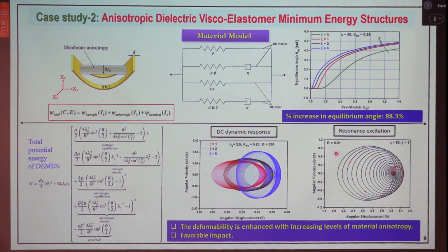Very simple use is that I will tell you, this Poincare map is used to characterize the stability of the system. If you are considering a non-linear dynamic system, if they form a closed loop, it represents that the system is quasi-periodic in nature. Stable quasi-periodic, you can say. If this Poincare map forms a large number of distorted points here and there, it means that the system is aperiodic in nature.